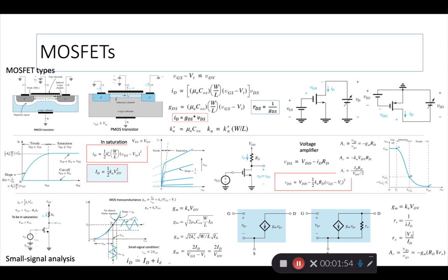The fact is that there is an insulation area right there, and it's a silicon dioxide based insulator that first and foremost creates a capacitor, right? By having a metal on the top and conducting material below, you put an insulator in the middle and you create a capacitor.